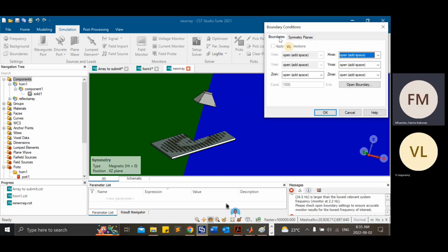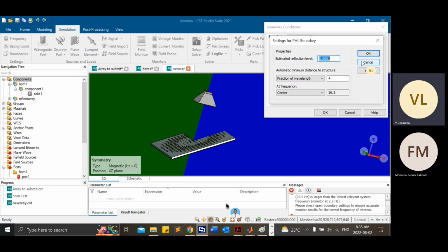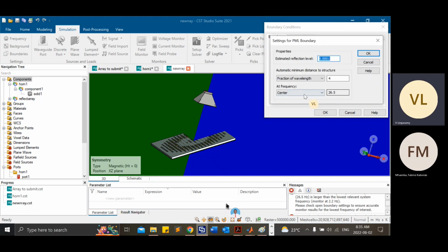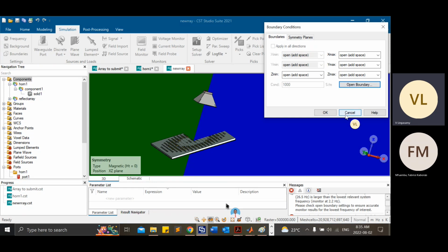That's also good. And if you want to quickly see what you have to do, you can give the highest frequency here so that the boundary size will be very low. Here you can give the highest frequency by means of user define. Define the highest frequency that you want, so that your boundary size will be low.